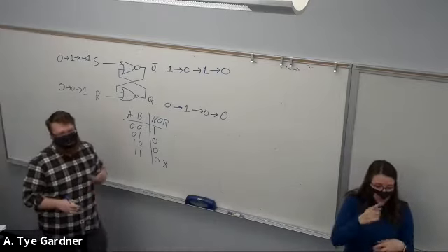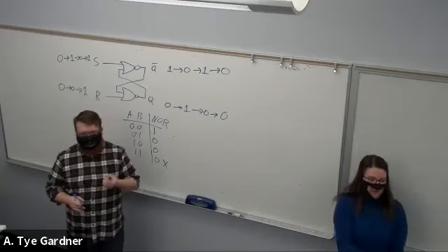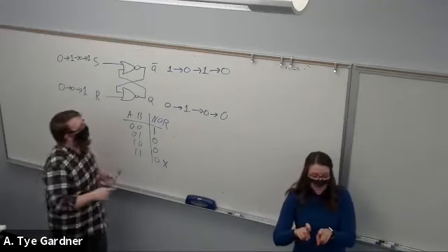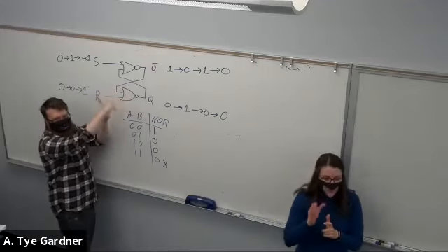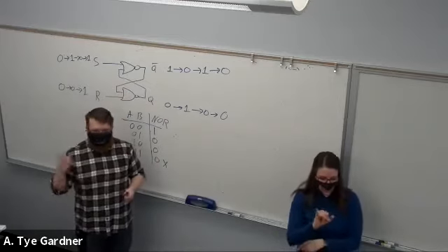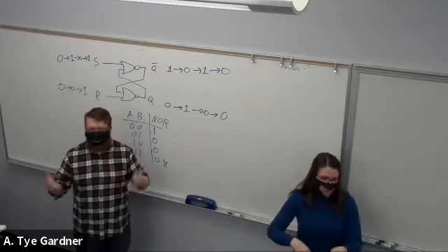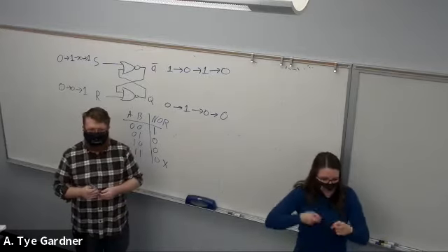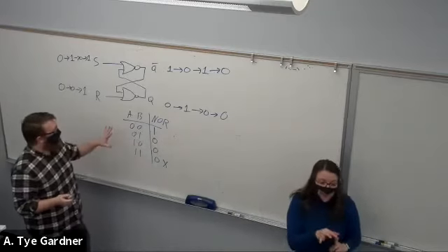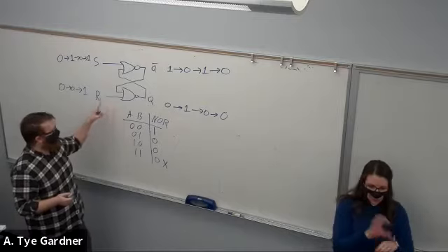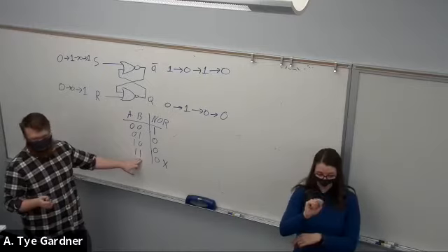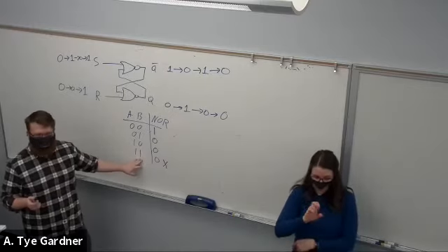In simulation, it's actually going to cause you a bigger headache than that, because what's going to happen is as fast as the simulation can go, it's going to alternate 0s and 1s because, as I kind of said, they're chasing each other around, and your simulation is just going to lock up and crash because it can't handle metastable conditions very well unless you have like a supercomputer that's designed for it. So if you build an SR latch in VHDL and simulate it, make sure you never deassert both 1s at exactly the same time.